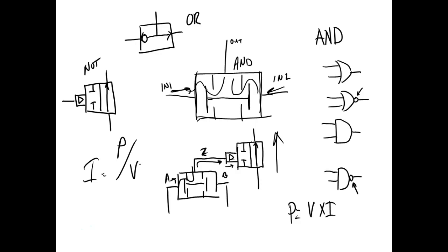So that means if power does not change, if my power in and power out are the same, and I raise the voltage, the current goes down. So if voltage goes up, I goes down. If I goes down and I push that through opposition, then I don't get as much pressure loss. Alabama Power calls it line loss. That's how much loss of pressure you have in the conductor. Okay, you understand that? So if I could step that up to 750,000 volts, I could send 750,000 watts of power with 1 amp of current.